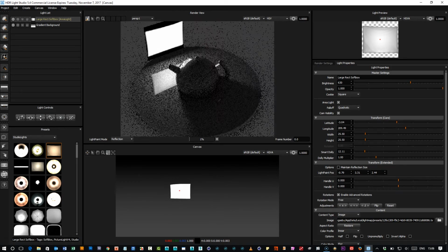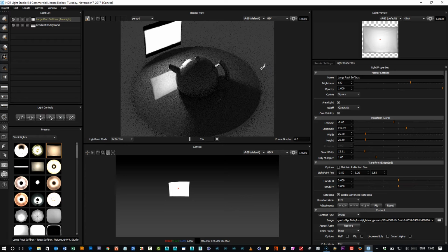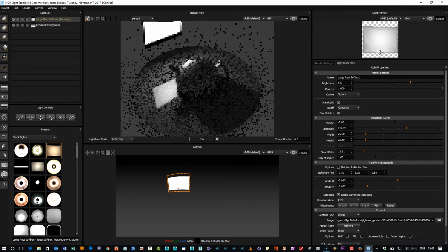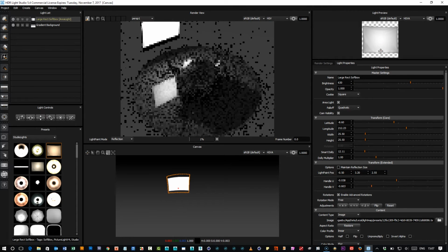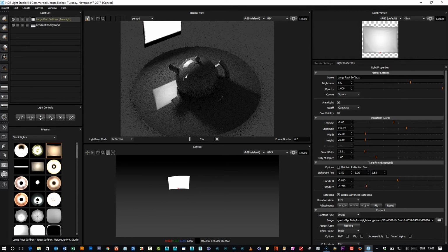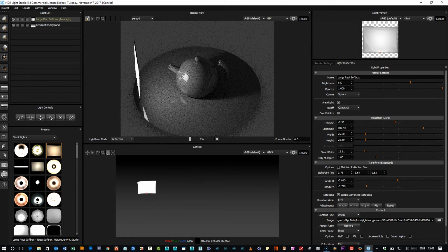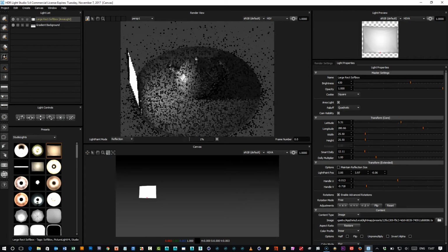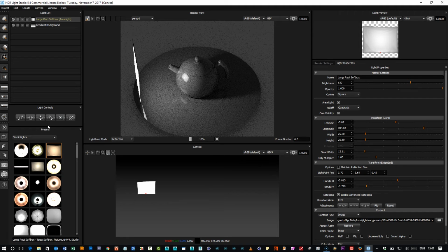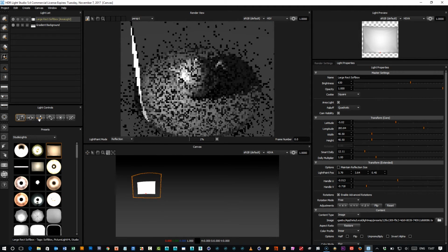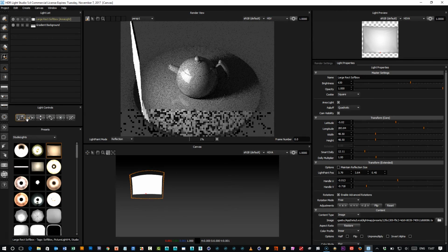And let's just put the light down here. So another thing to note is with the positionable light handle, if I was to move the handle, you'll see the light interactively updates in terms of its positioning. So if I put the handle on the bottom here, and then I was to click on here, I've now been able to position the start of that light reflecting in my model by its bottom edge there. If I do things like scale the light, that will then also happen from that light handle position.